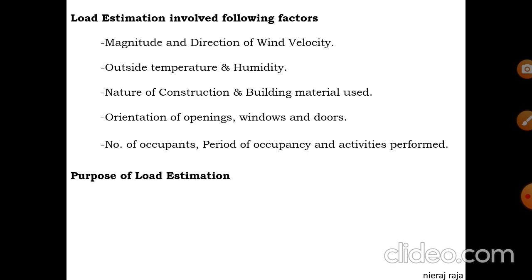Now, the purpose along with designing and selection: the first one is the load profile over time. Whenever you go for load estimation, you find out different curves and profiles of the load: how much the heating load is, how much the cooling load is, and what the heat gain is. That is the initial part of your load estimation. Then comes the peak load, in order to evaluate the maximum load to size and select the refrigeration cycle components.